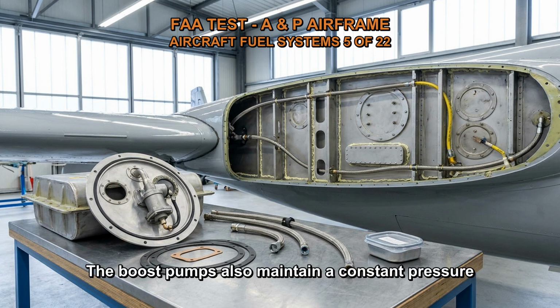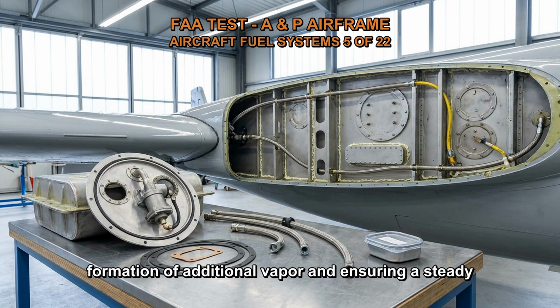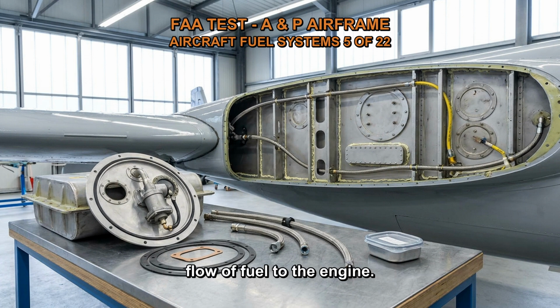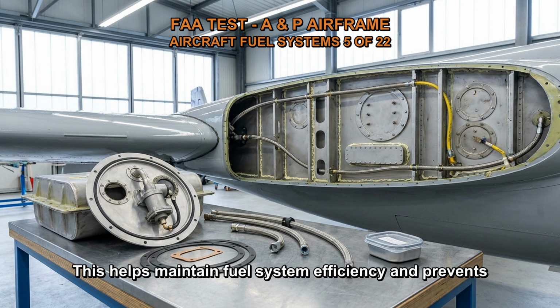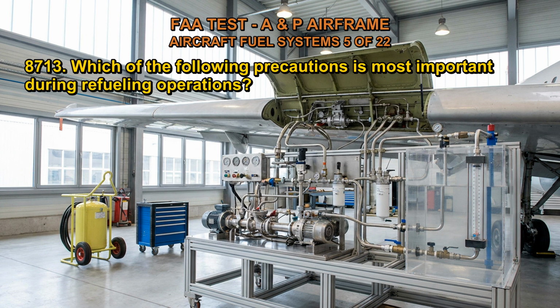The boost pumps also maintain a constant pressure on the fuel in the lines, preventing the formation of additional vapor and ensuring a steady flow of fuel to the engine. This helps maintain fuel system efficiency and prevents potential issues caused by vapor lock or fuel vaporization.